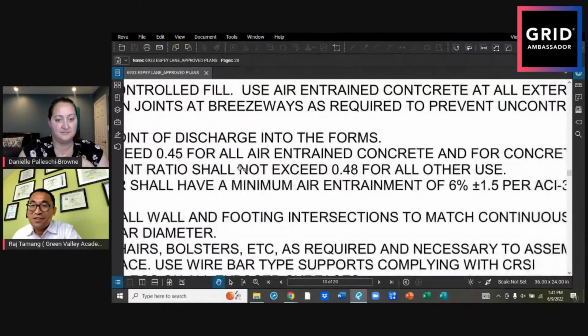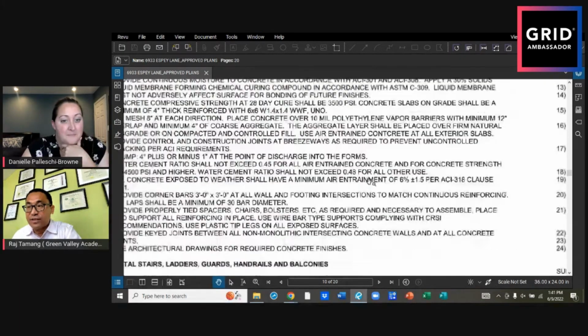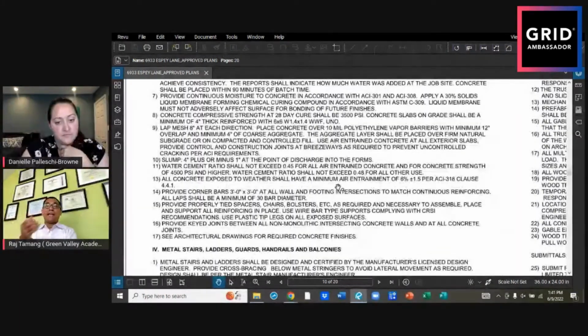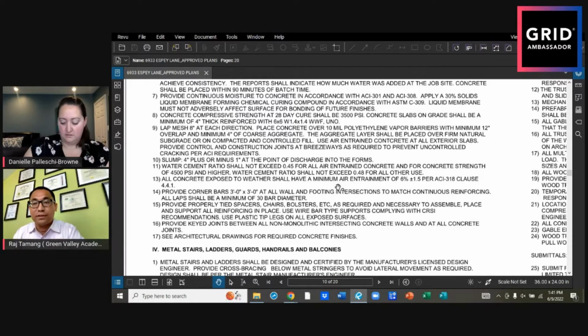That's a good question. So all outside concrete is air-entrained concrete. This is a little bit more specific. Like I said, you cannot use the same concrete that you use inside a house for outside, because of the different temperatures, cold and hot. Also, especially if you are pouring a driveway in the wintertime, your vehicle will bring all kinds of salt and chemicals, right? And that concrete can crack.